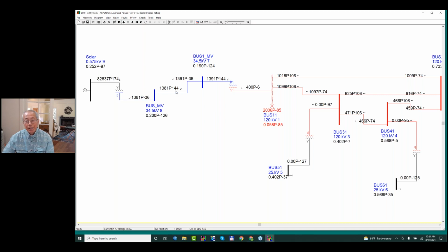Okay, Sherman? Yes. There's a question here that says, do you have to model at that low voltage level, or can you aggregate and just make it on the 34.5 kV? Will that work the same? That's a question from AEP. I think the person asking is whether they really need to model this transformer. Because this transformer brings you from 575 volts to 34.5 kV, and my answer is definitely yes.